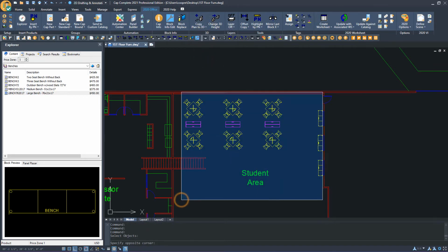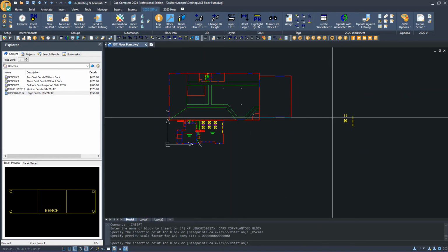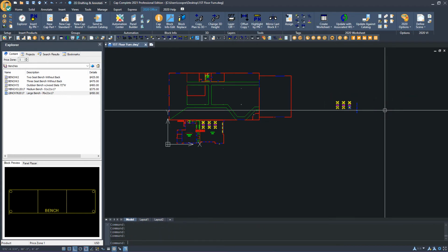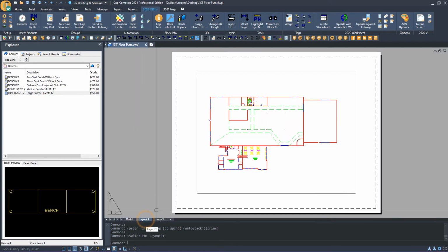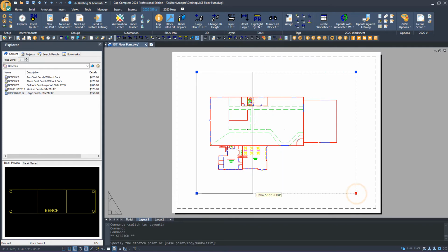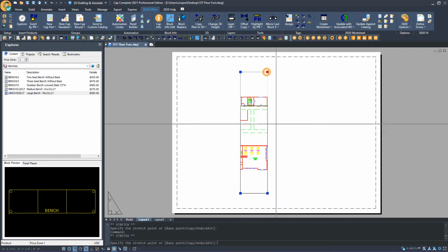And so this would allow us to have a plan view, and then out in the outside portion of our drawing space, we can copy a 3D, and that way I can go into my paper space, and we have viewports that we can adjust to create the different views that we're looking for.